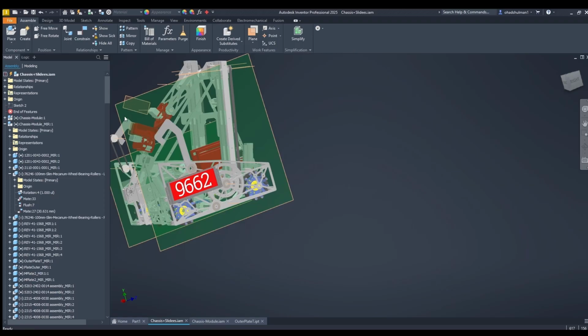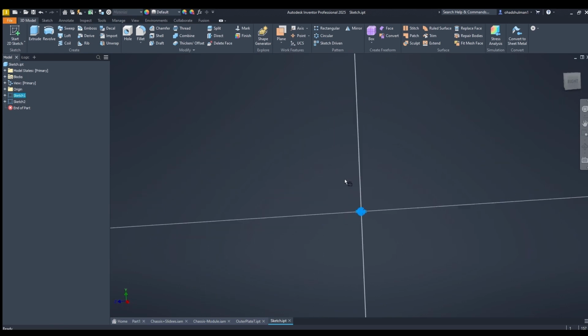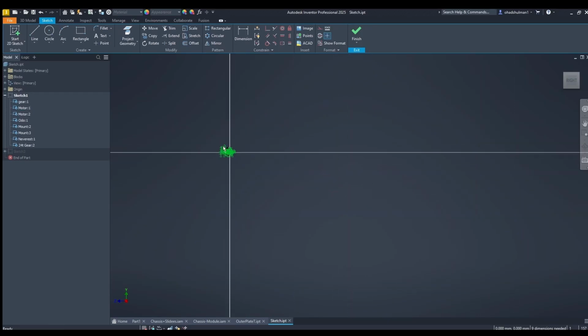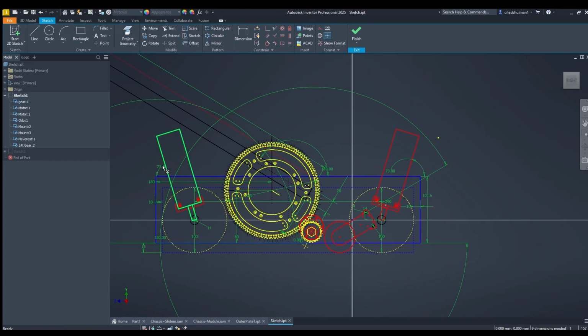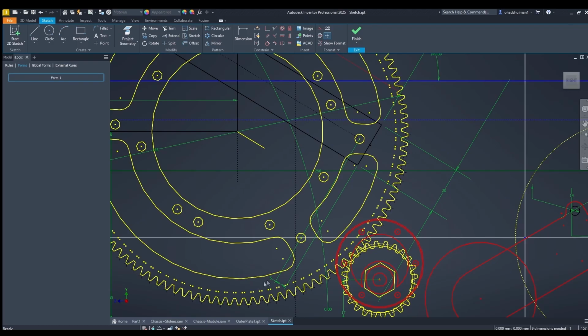Now this one might not be a simulation. Inventor doesn't do it for you, per se. You can see, once I zoom in, I have a full sketch of what my robot will look like. That was an early sketch of our robot. You can see I have the motors and motor holders, and our pivot slides, and the motor that powers it, the slides themselves, and the odometry pod. These yellow circles are the wheels. All of this is accurately sized.